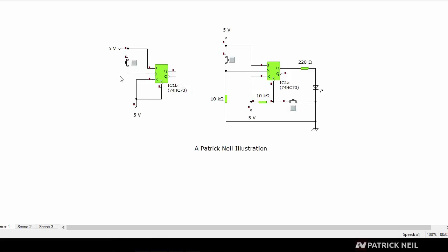Now, if you carefully look at this flip-flop, it is a positive edge flip-flop, so it reacts from a low to high. So the signal on this input, which is called the clock input, and the way you can know the clock input in any circuit is that it has this little arrow on it. So anytime you see this little arrow, that is the clock input. And when it's a positive edge, it will look just like this. However, if it's a negative edge, it will have a bubble, just like this little tiny bubble here would be on the, right here. Right?